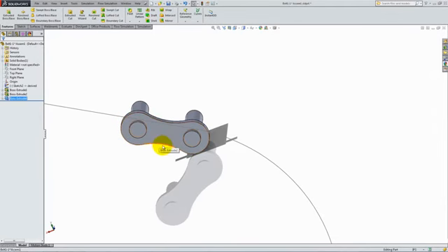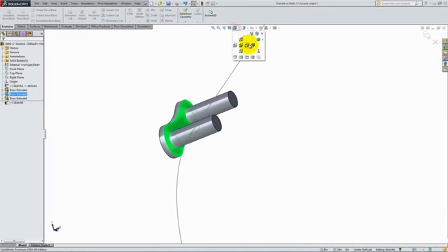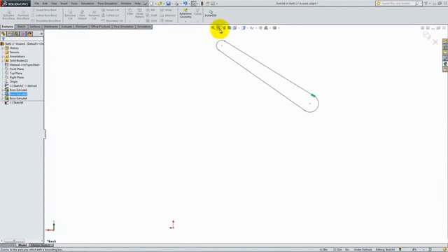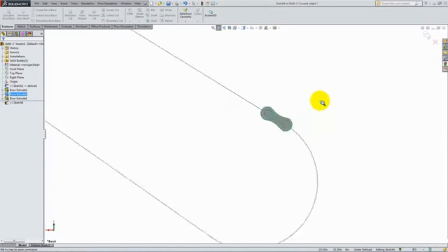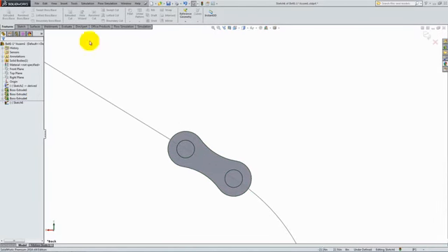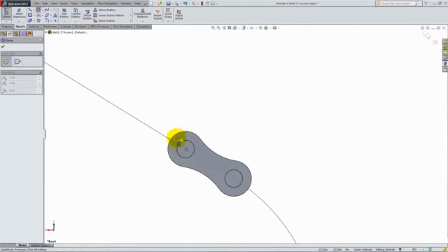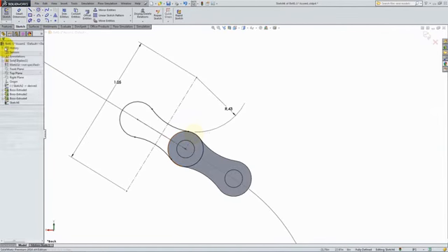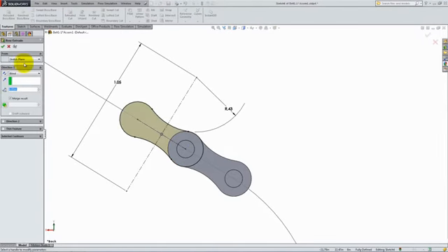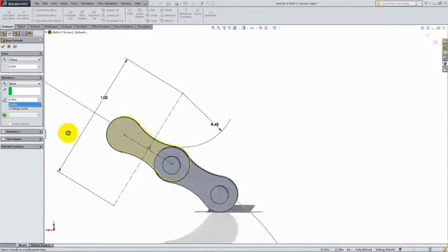Now start a new sketch on the back side of the second feature. Use the same geometry that you used in the other sketch, but translate it so that the right circle is concentric with the left arc of the previous sketch. Use Extruded Boss and in the start condition add an offset of 0.03 inches. Keep the depth of 0.05 inches and click OK.